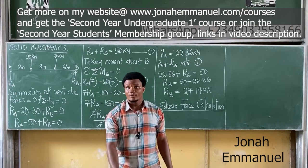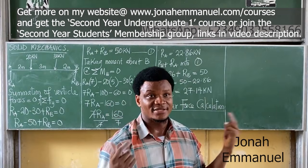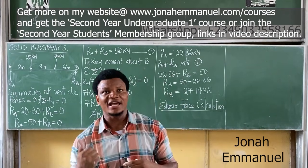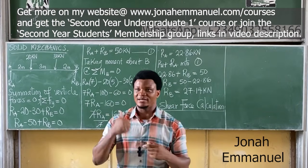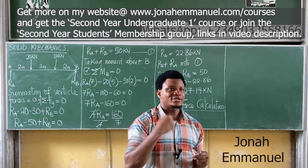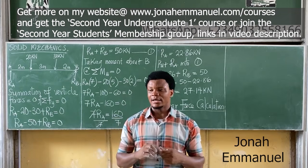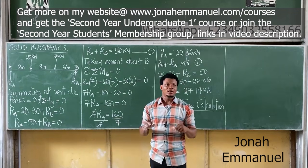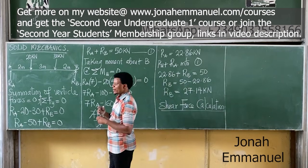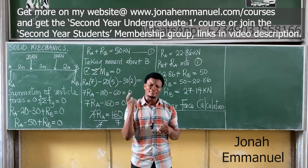Please just listen to this and get how it works. Your first task in every shear force bending moment diagram is to get the value of the reactions, which we've done here. Your second task is to do a shear force calculation. Now listen, I won't waste your time. I'll go straight to the point. When you're doing shear force calculation, I'll be taking intervals at specific points on the beam.